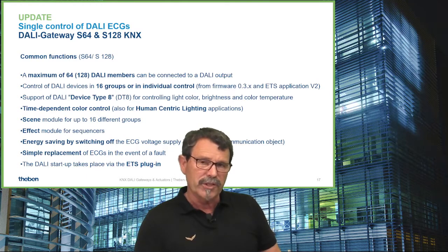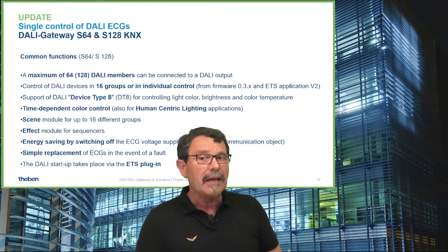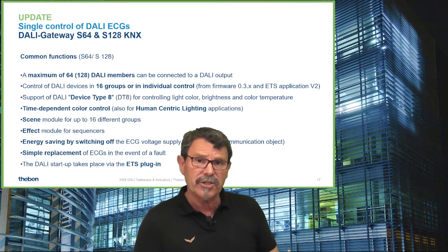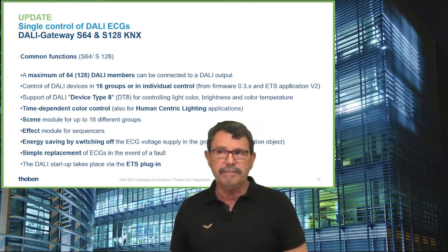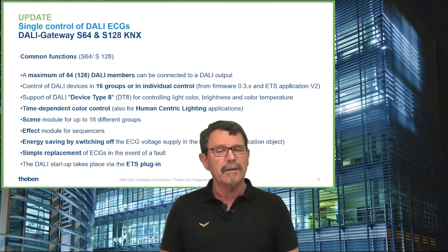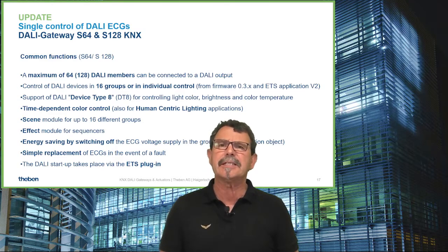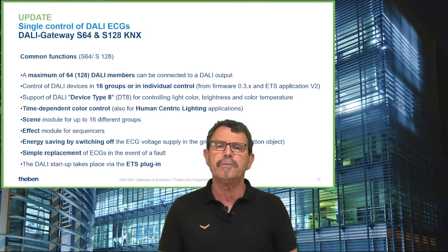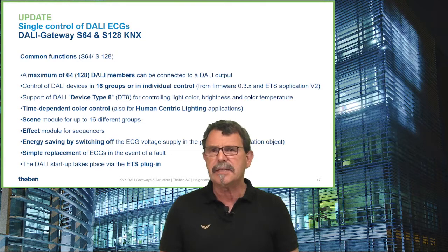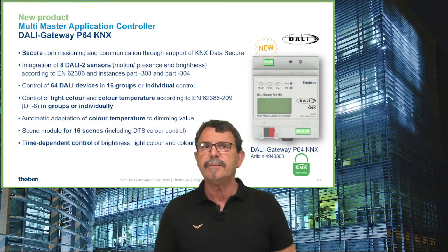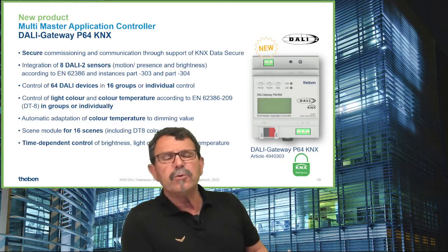First of all, all our DALI gateways, including the new broadcast DALI actuator, are supporting you with data point 8 communication. That means any kind of colors we can control, so no doubts about it. All of our DALI products are supporting you with data secure, especially when it comes to bigger, more prestigious projects like schools, hospitals or whatnot. Then, if you like or if you need to, you can communicate on KNX Data Secure.